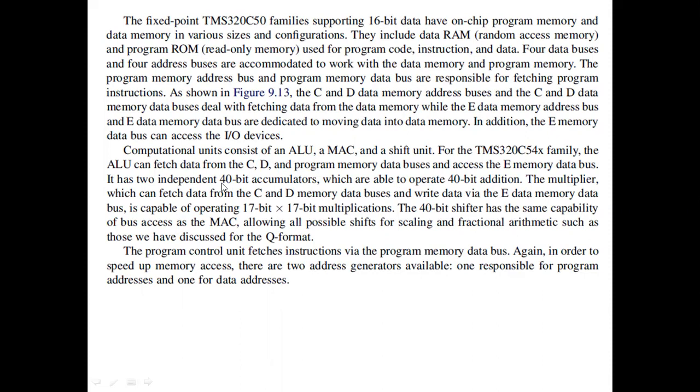So DSP is all about MAC operations. Having additional bits more than 16 will let you loop through larger sets. If you want to perform a 1024 point DFT, you can imagine, if your data is 16-bit and you may have to do 1023 additions, your answer may easily increase by another 10 bits. So that is why a larger accumulator size helps. Afterwards, it can be broken into pieces of 16, that is 1, 2, 3 pieces, and stored.